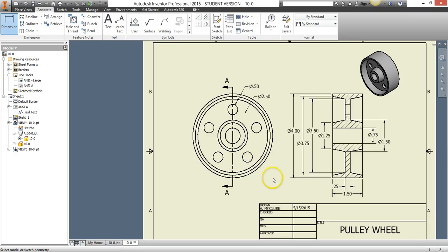Because this is a little bit different than what we've done in the past, I'm going to go ahead and show you guys how the dimensions should look. In order to get the diameter dimension, I just retrieved dimensions, and all of these dimensions appeared. The only two that I really had to add or modify were these two because it just did it in half. When we created the drawing, we did not do from here to here and from here to here. That was in order to create this shape on both sides. We had to mirror that. So I went ahead and added those dimensions. Other than that, you guys should space these out, and they're going to be spaced out a little bit more than normal.